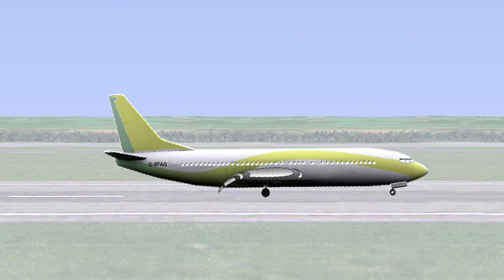Initiate reverse thrust as soon as possible after touchdown of the main wheels and target the rollout to stop well short of the end of the runway. Leave a margin for unexpectedly low friction due to wet rubber deposits or hydroplaning.